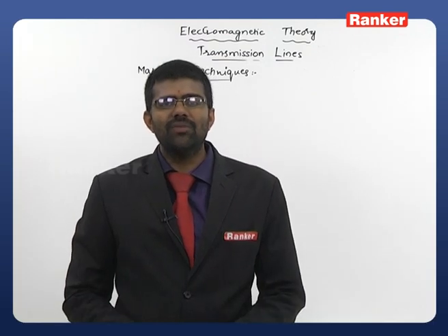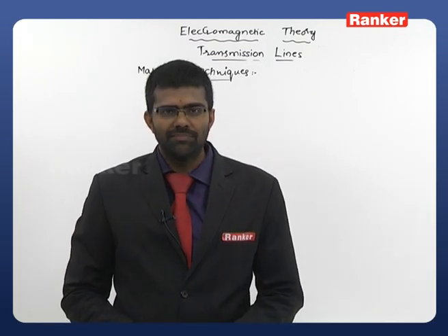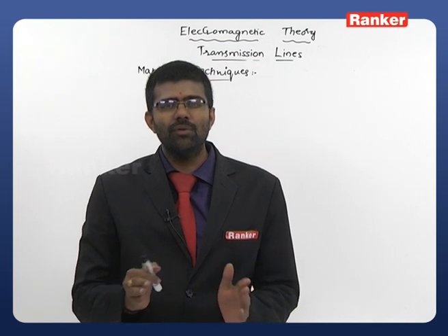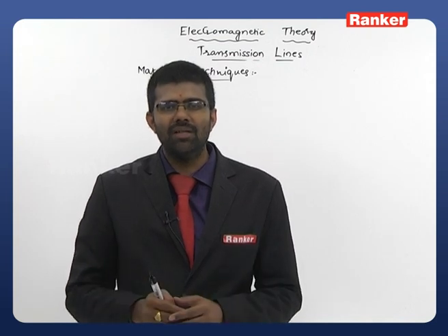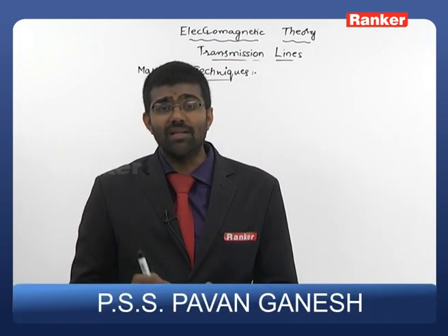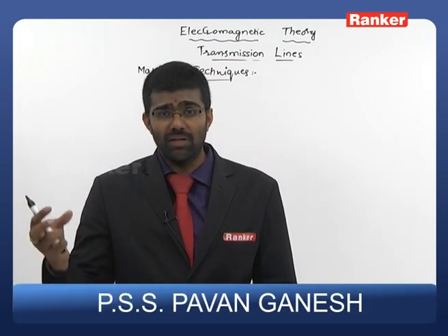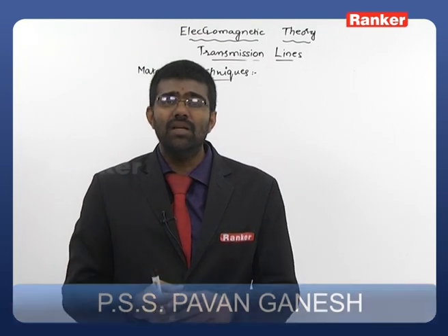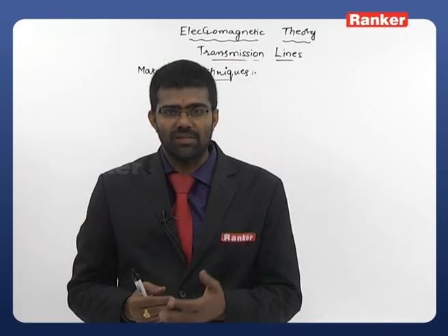Now we will discuss different matching techniques for the transmission line. Already we observed whenever ZL is equal to Z0, obviously that is a matched line, and the maximum power will be transferred from the transmission line to the load. Whenever ZL is not equal to Z0, that is, the load we are connecting is not matched with the transmission line, some power will be lost and you will get some reflections, right?